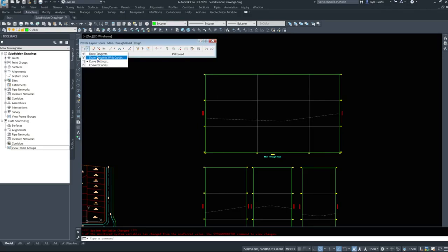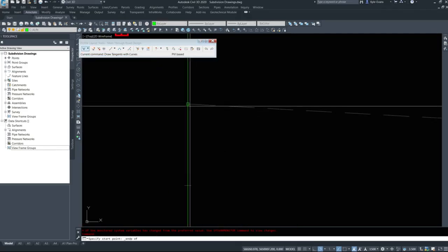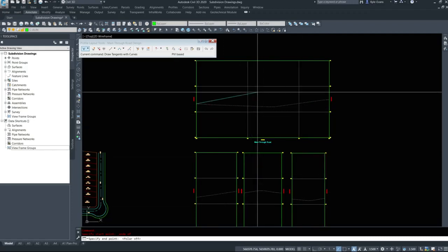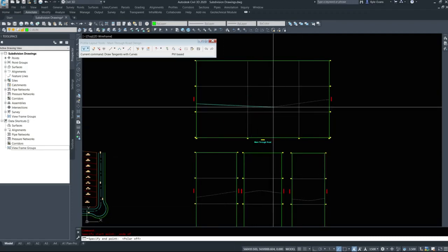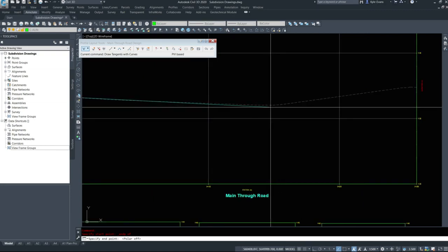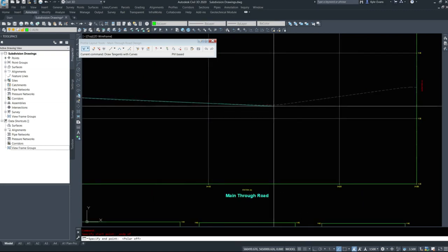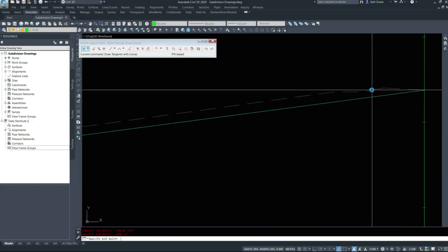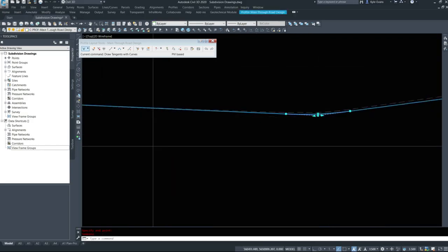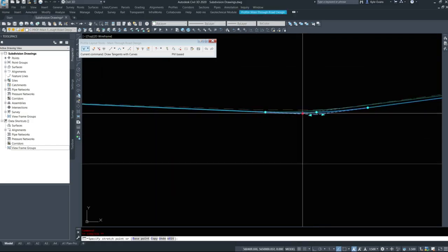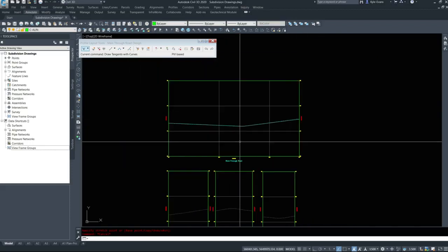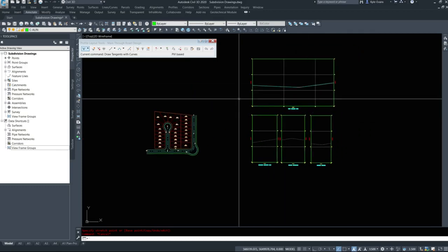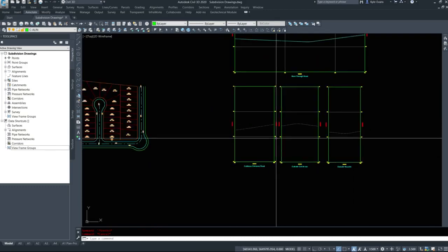And then we can draw tangents with curves. Now I'm going to snap to the end of my existing ground here, and I'm going to again trace it as close as I can, like our highway design, so we don't have to worry about cuts and fills. So I'm going to come down here, click and create one vertical curve, and probably come up towards the end here. And then I'll hit escape, and then I'll adjust this a little bit to better match that. Again, just grip editing is fine. So again, very simple for that one. Very simple for all of these really. And then I'll close that and do this next one.